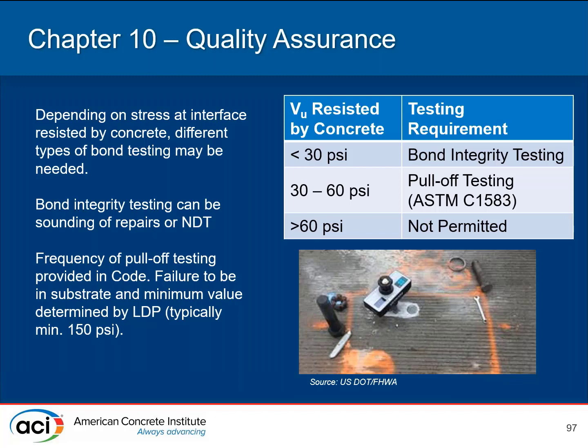The idea is you give them a little bit of age and let them shrink so that the stresses develop at the bond. Then you can go out and sound them, and hopefully everything's still in place. If they're not, they need to be redone. Sounding is the most common and simplest way, but you can also use non-destructive techniques if appropriate, such as ground penetrating radar, impact echo, ultrasonic pulse velocity, some of those fancy things.